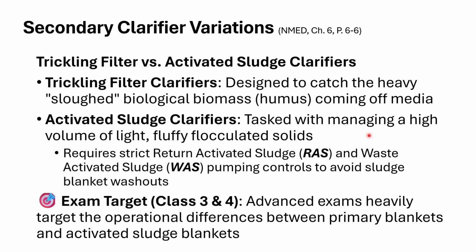Okay, so with an activated sludge secondary clarifier, we're dealing with a volume of light, fluffy, flocculated solids. Think of these little tiny, very light mud snowflakes that are accreting together and falling to the bottom of that clarifier.